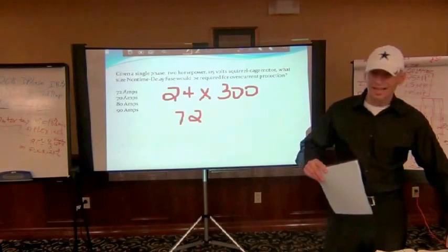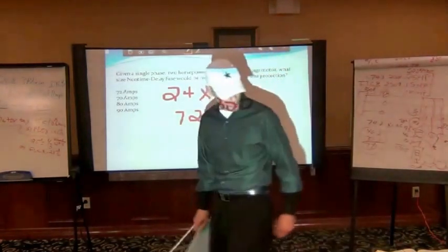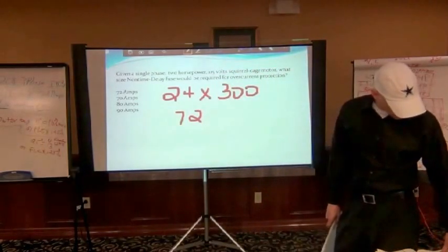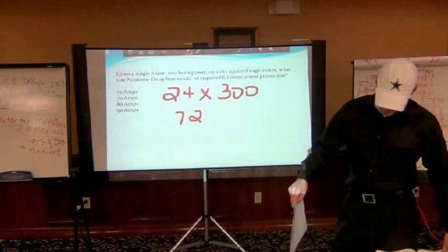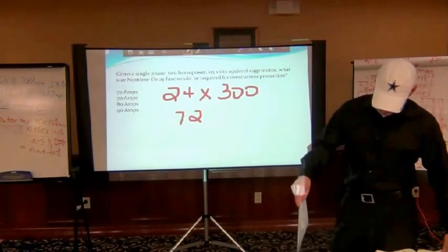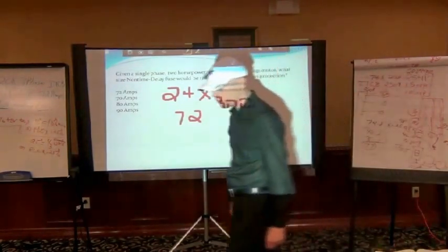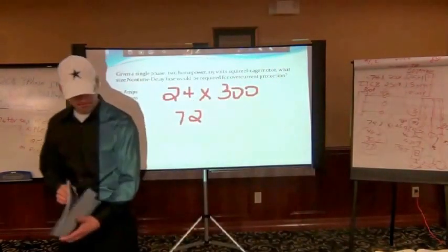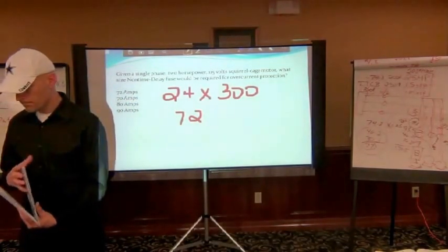And then add the sum of the other two motors, which was a 10 and a 5 on the same one. So the 10 horsepower would be 14, and the 5 horsepower would be 7.6. So 40.8 plus 14 plus 7.6 is 62.4. What did you get?